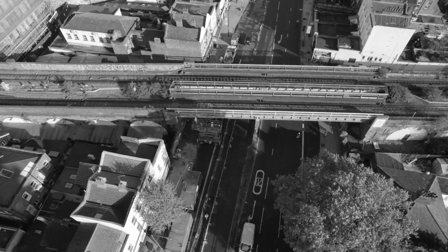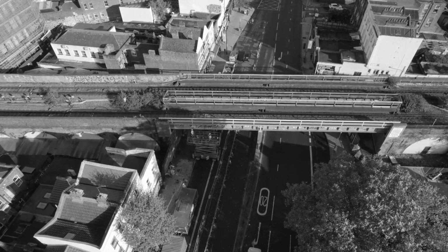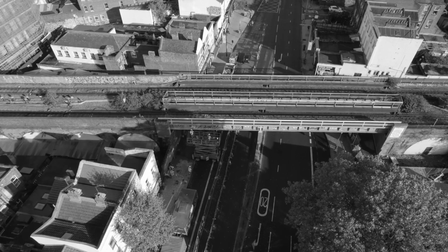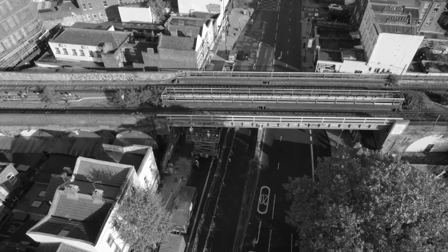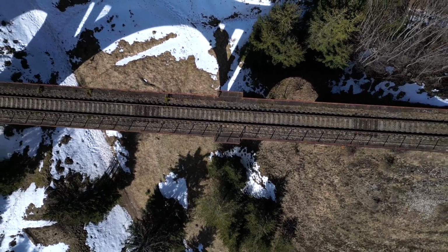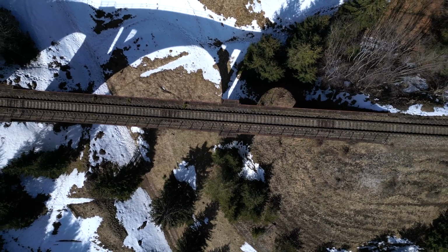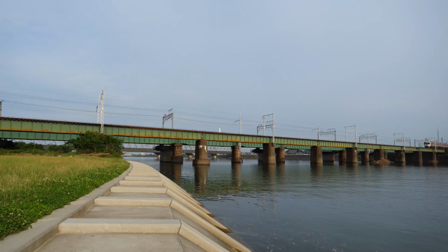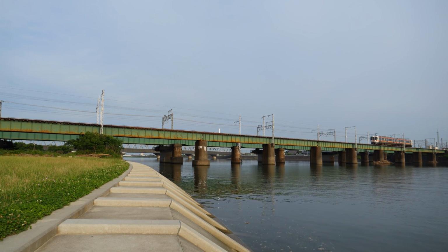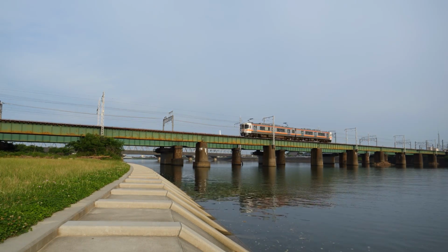Typically spanning roads, rivers, or underpasses, these bridges use steel beams or plates with direct fix or ballasted track tops. Steel expands and contracts with temperature, and while this is well understood structurally, it can impact the track also. Network Rail and RSSB documents highlight that if expansion is not properly managed with the correct bearings or joints, it can transfer stress onto the rails and fastenings, leading to creep or distortion. Rail creep and geometry shift over metal decks has been observed in inspection records, particularly where expansion isn't being properly accommodated.